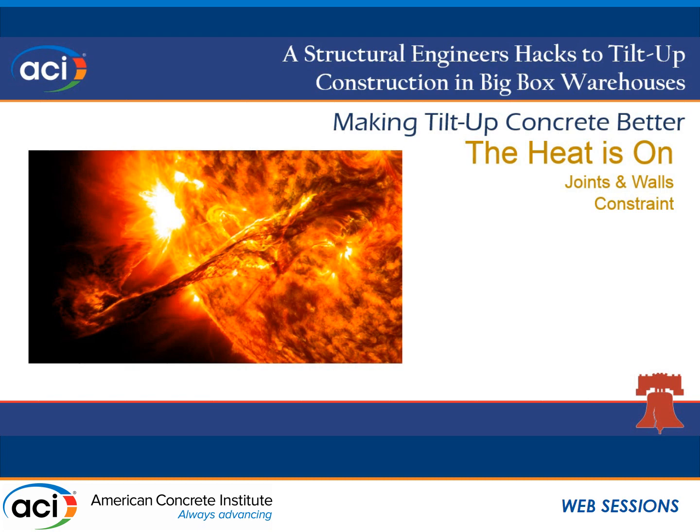The other thing is, if you have a building that is, say, deeper or larger than what your calculations say you need an expansion joint for, but you can't get one for whatever reason, and you have to constrain your building for thermal expansion and contraction and not let it expand, you have to deal with that force. But I'll tell you, you're chasing your tail. It's kind of dangerous because the amount of force developed is proportional to the area of steel, PL over AE, right? For elongation, the only way to resist it is to add more A, which adds more force. So hopefully you don't chase your tail all the way to the ground.